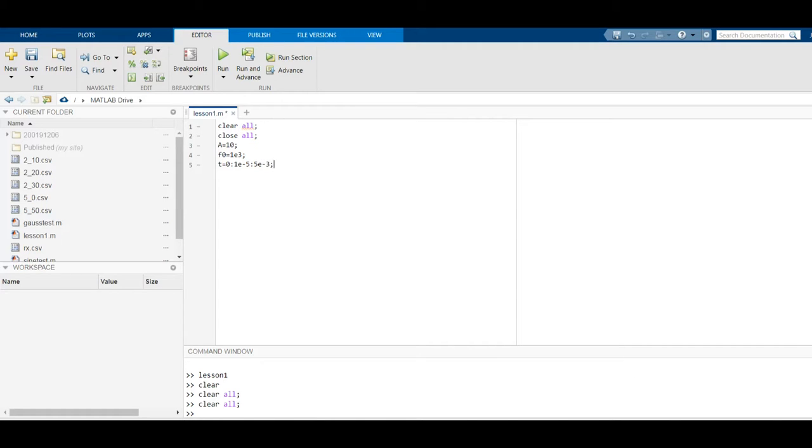You can see the frequency f0 is 1 kilohertz, and the time for one complete wave will be 1 by f0, which is 1 millisecond, and when you plot it till 5 milliseconds, you are going to get 5 cycles. And why is this important? Why is the middle parameter important? That's very important. I'll show you different variations, different waveforms that come up when you vary this. So these things are very important.